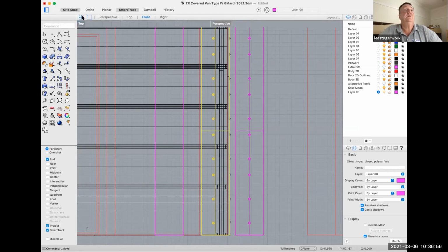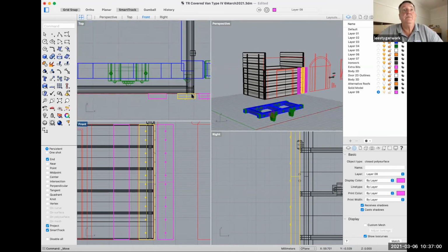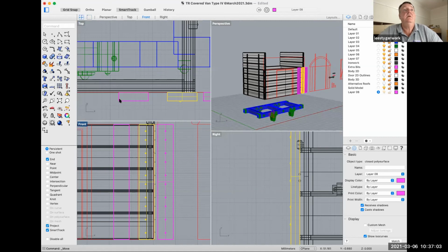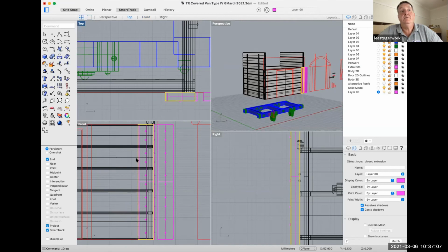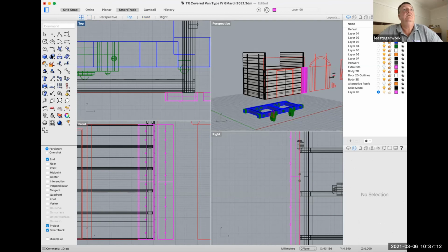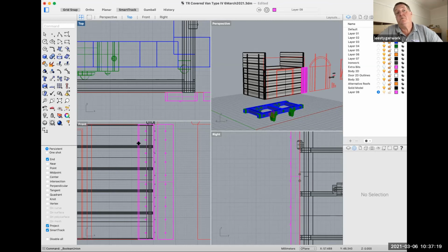I just want to make sure it has actually done as it's supposed to up here, which it has. I'm bringing this guy now to there. So it's overlaid back where it should be. I'm joining those two together. And that was the trick I wanted to show you, which was because we moved it 1/4 of a mil, it was 1/4 of a mil too short. By creating a secondary solid, you can just join it to create the right length again.